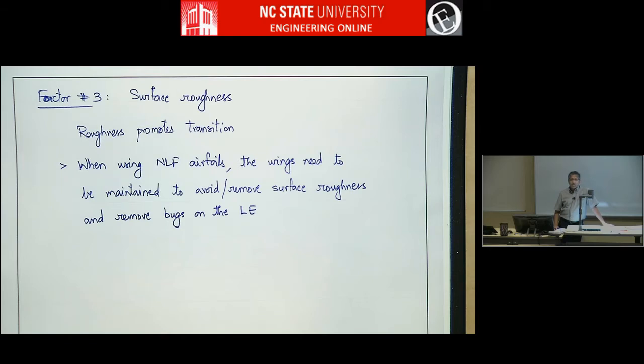So especially when you use laminar flow airfoils, right? Wings have to be maintained. The surface smoothness has to be maintained. So this affects how the wings are fabricated, which is why NLF airfoils have started becoming popular after the advent of composite construction.